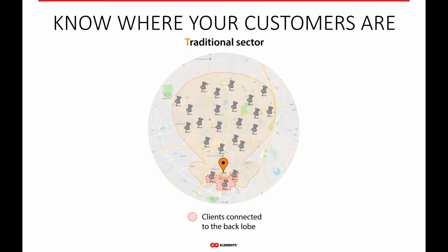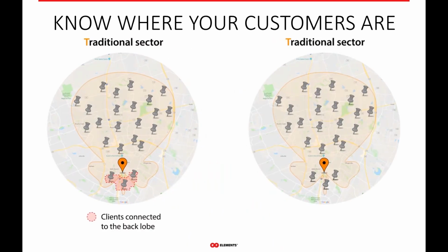So when your network is set up this way, it could be a problem in transitioning, because once you deploy your horn antenna, you will quickly find the customers that were not connected to the front of the particular sector that you thought they were connected to, and therefore it will cause an issue because customers will drop off, right? Since we have no side lobes and very good front to back, you won't be as efficient when you're transitioning your customers to horns if you don't know where they are. So this is a really important first step in transitioning to horns.